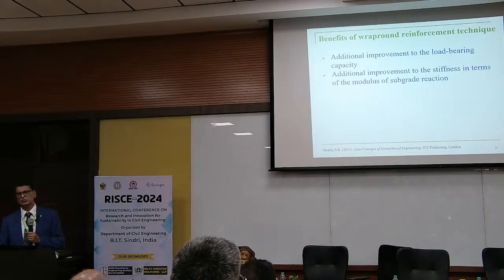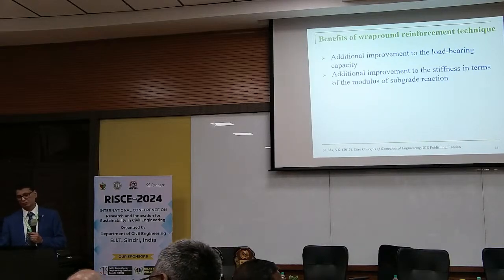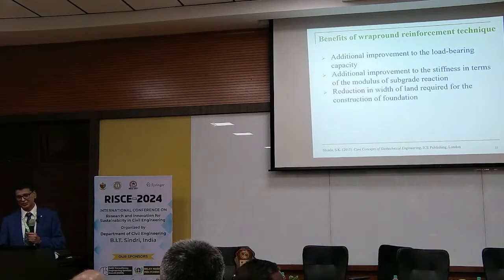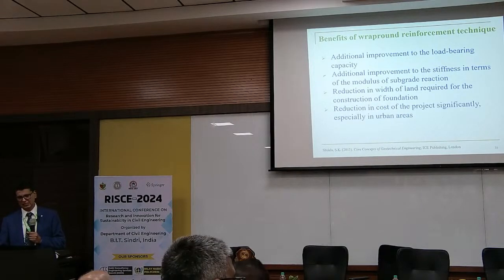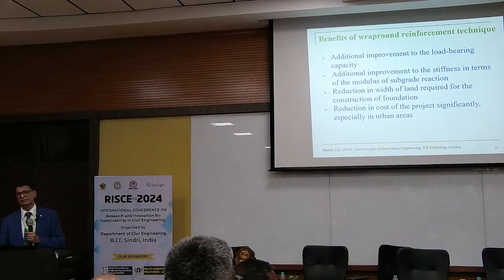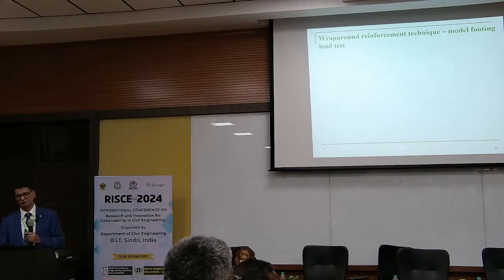Finally, this is the conclusion part. Although I have more slides, let me summarize here that we are getting additional improvement to the load bearing capacity, additional improvement to the stiffness in terms of the modulus of subgrade reaction, and a reduction in the width of land required for the construction of the foundation. This technique is really very useful, particularly in our urban areas or even in hilly terrains, because we don't have land there, and sometimes we still want to strengthen our foundation.